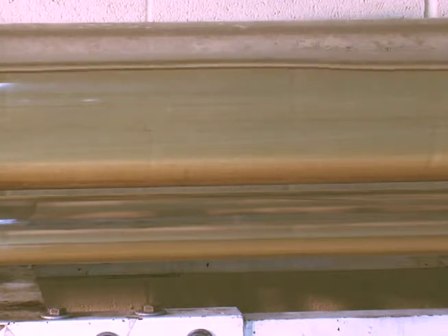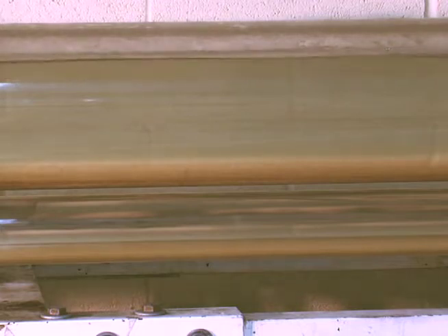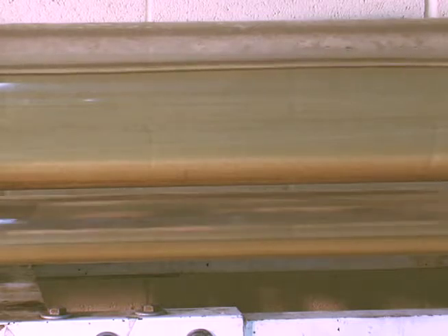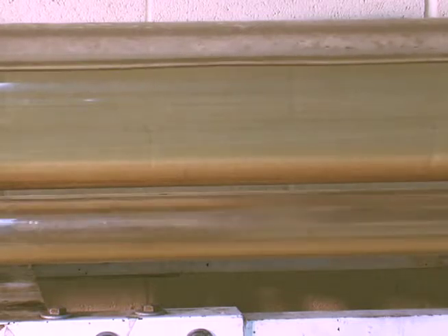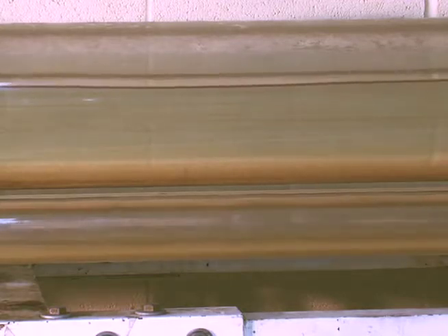Now 17 MCF per day of air is added to the 628 barrels of water per day. You'll notice in the upper tube that it remains a segregated, stratified flow pattern, but in the lower tube, you'll notice that we are now transitioning to a plug flow where you saw some large bubbles of air go by. And now we're transitioning into slug flow, where frothy slugs are going to pass by.